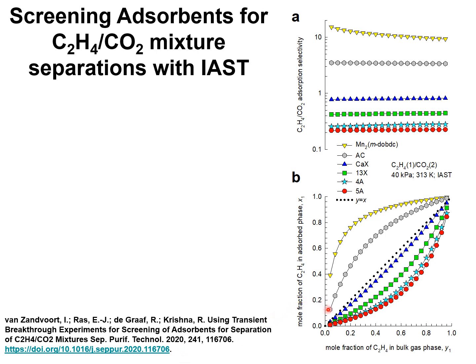The choice of activated carbon is understandable because the IAST calculations show that activated carbon is ethene selective. However, the IAST calculations show that LTA5A zeolite is selective to CO2 over the complete range of feed mixture compositions.